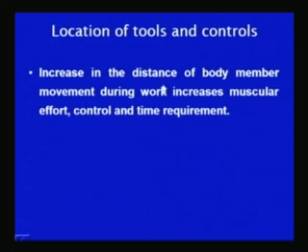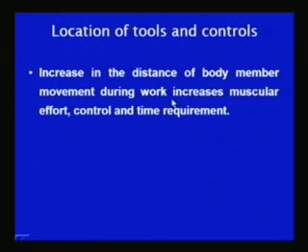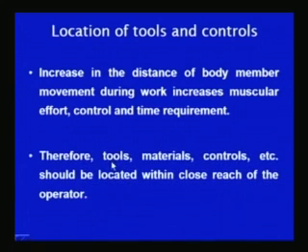So, an increase in the distance of body member movement during the work increases the muscular effort, the control and the time required for carrying out the job, and that is why the tools, materials and the controls should be located in such a way that the distance of the body member movement during the work is minimum, so that the related muscular effort, control and the time required can be reduced. Therefore, tools, materials and controls etc. should be located within close reach of the operator.